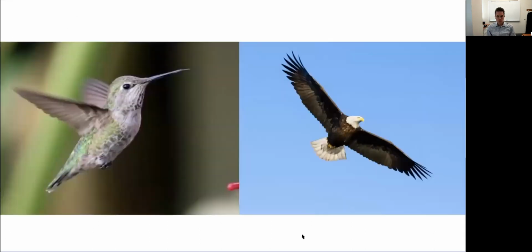Okay, so actually let's look at some pictures here. I mentioned birds. These are 2 good contrasts. A soaring bird like an eagle, large wingspan, efficient. It can fly for a long time without doing much. It doesn't have to flap because it's got that long wingspan, low induced drag, very efficient. On the other extreme, a hummingbird, very small wingspan, has to expend a lot of energy, but like in all things in engineering and aircraft design, there are always these trade-offs.